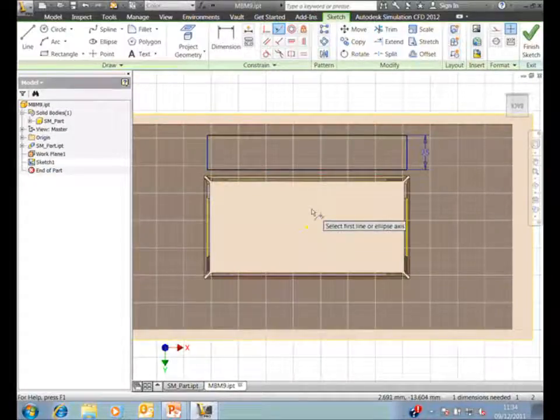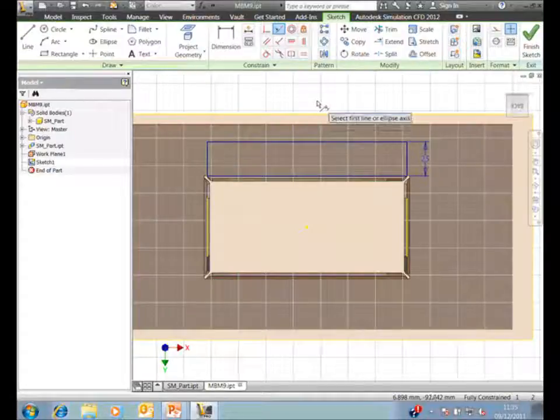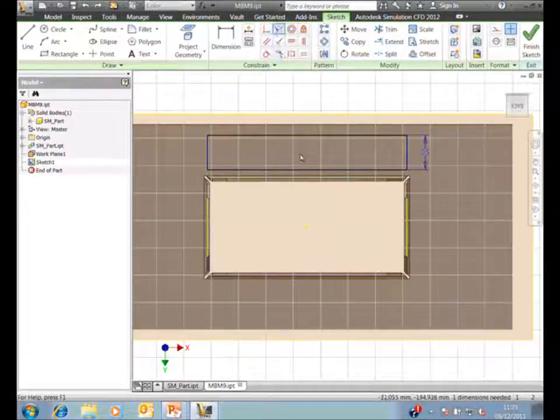This is very useful. It avoids us having to work with associative adaptivity in assemblies, which can slow your assembly down if it becomes very, very large. So I'm using collinear constraints just to nestle my sketch against my component.